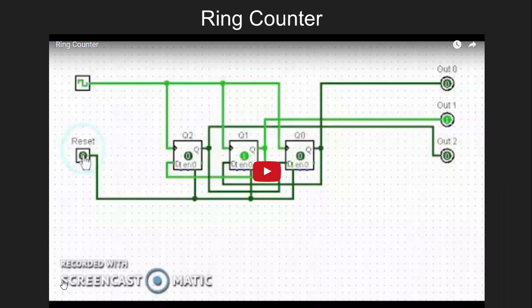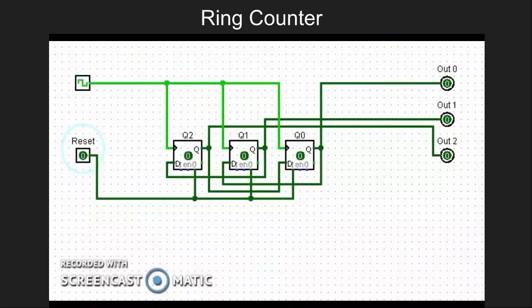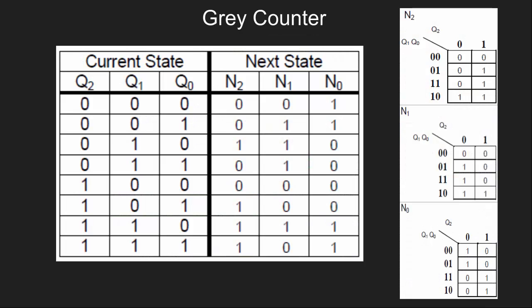The implementation of these formulas requires no gates whatsoever. They're simply a function of one of the other states. So it goes from 1 to 2 to 4 and begins again. Let's watch it in action. First we have to hit the reset button in order to put it into state. Then it begins to cycle through. If the reset button is held, it will maintain the first state.